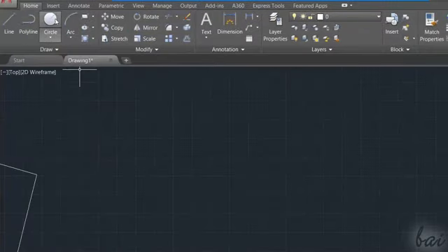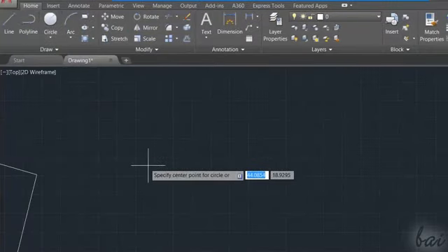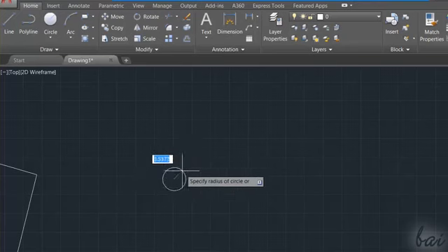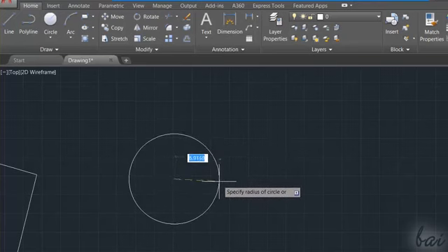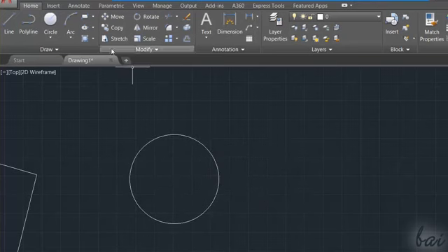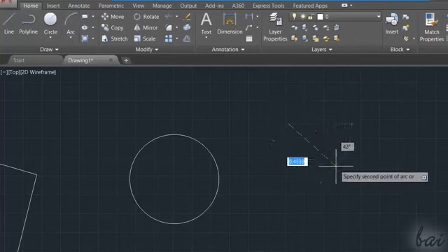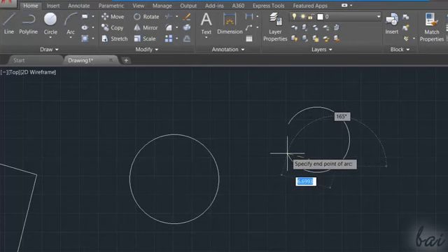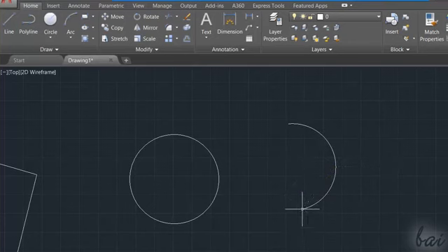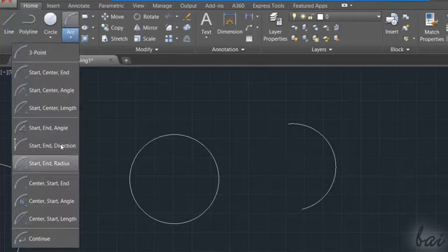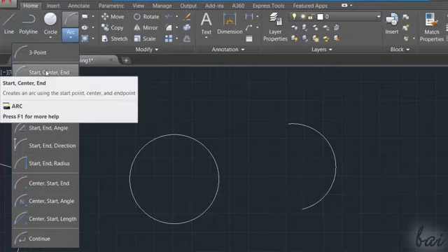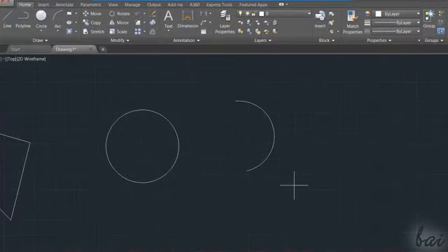Use the Circle tool to draw circles by fixing the first point to fix its center and another to fix its radius. Use the Arc tool to draw arcs by fixing 3 points on the workspace. In particular, there are several ways to draw circles and arcs, all contained inside their white arrow on top. Choose the proper tool depending on what you need case by case.